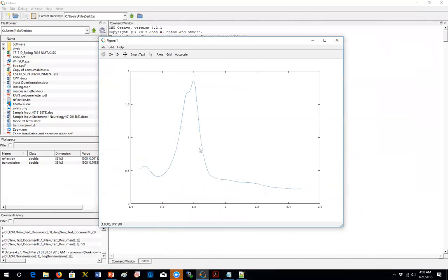The deviations between our plot and their plot are mainly because of the different choices of the dielectric coefficients. We did not use their gold selection, and also the ITO. We basically did everything with NanoHub's material database. But in the end, it's very similar, and we have a very similar plasmon resonance that determines the extinction.